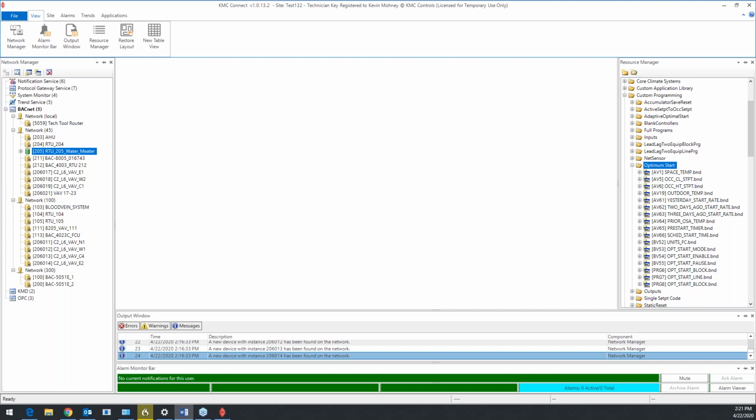Well, I think to me it adds ease of troubleshooting. If I show up to a controller, I've plugged in with my router, and I want to know what's going on with the active cooling set point, and I see a write from priority 9, I can kind of assume that's coming from Control Basic. If I see a write from 8, maybe that's coming from a graphic or an override.